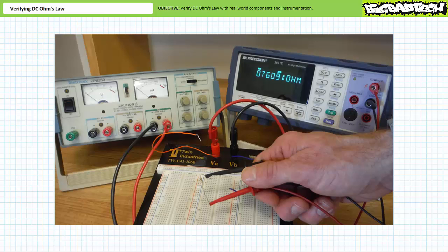An ohm meter measuring the resistance of a resistor matching this description demonstrates that it has a resistance of 760.9 ohms, well inside the expected tolerance range. This being said, given this resistor has a slightly higher resistance than its nominal value, we might understandably expect our observed current to be slightly lower than our theoretical calculations might suggest.